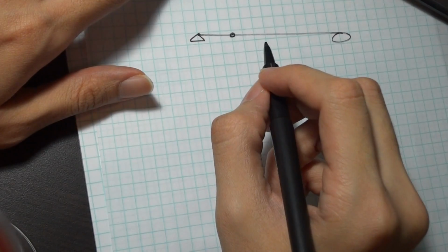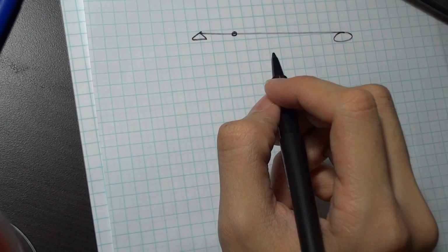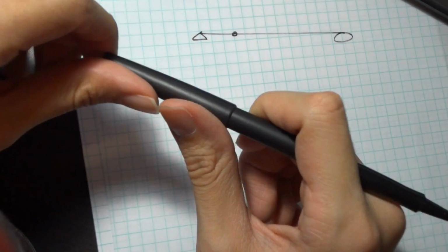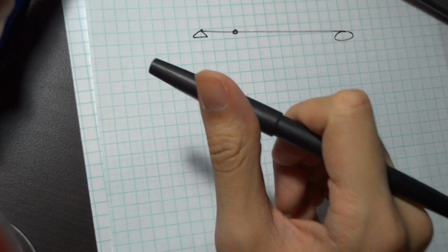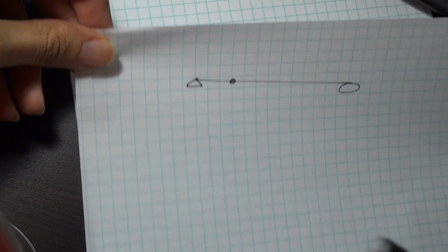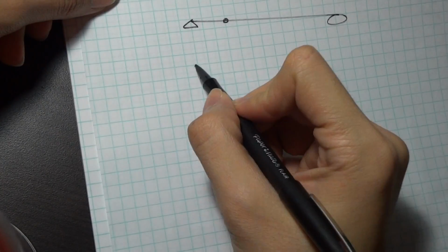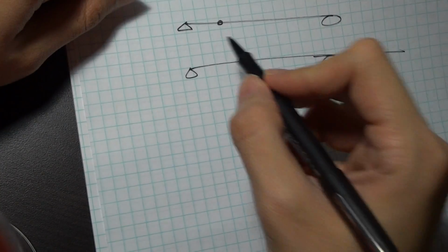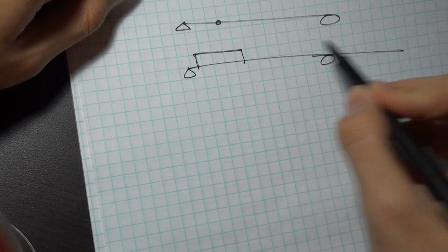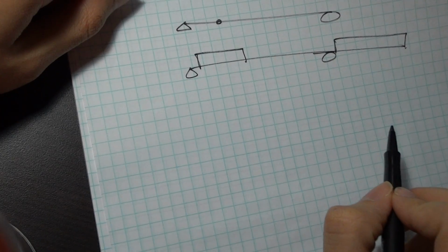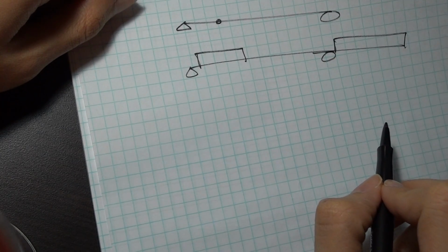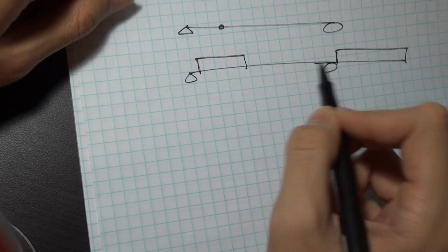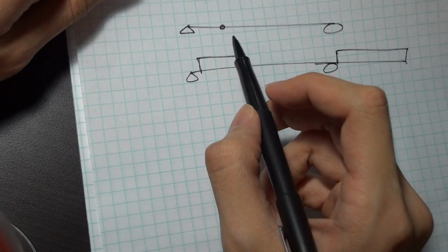In this case, I'm interested in the shear at a single point due to a load at any point on the structure. This is primarily useful for bridges, where you're interested in, for example, groups of cars, and due to traffic flow problems, you might have seen this in a little bit of intro to transportation engineering. You could have a scenario on a bridge where maybe the critical case is when you have a small group of cars here and a small group of cars here. Finding influence lines would allow you to identify what load cases would give you the largest value at a specific point.